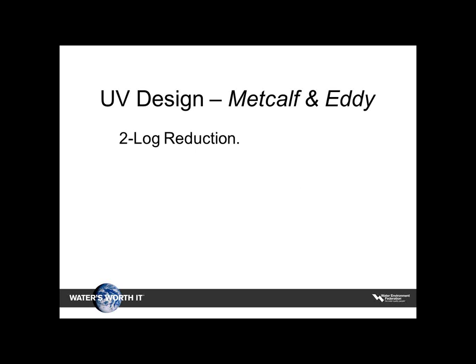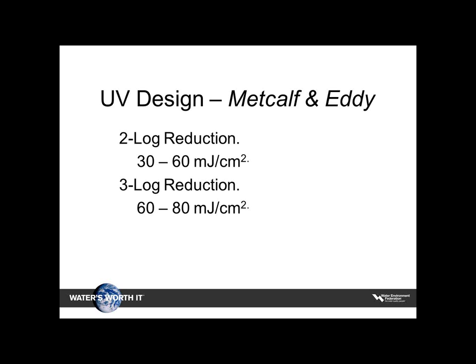But what I want to talk about is one of the things they speak to in there, and this may percolate into regulations. If you want a 2-log reduction, they're recommending anywhere from 30 to 60. So you may see these numbers, and now you at least know where they came from. If you want a 3-log reduction, they're recommending between 60 and 80 millijoule dose, and 4-log reduction